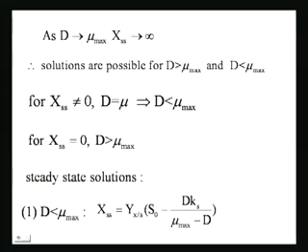So, in bioreactor systems, in biochemical engineering, they say that a very large dilution rate means that the system is being excessively diluted, and as a result cells cannot be grown. But if you look at it from a chemical engineering point of view, then we convert it into the residence time. So, D very large means residence time very small, which means that the cells are not getting enough time in the reactor to grow. Okay. So, that is why it happens.